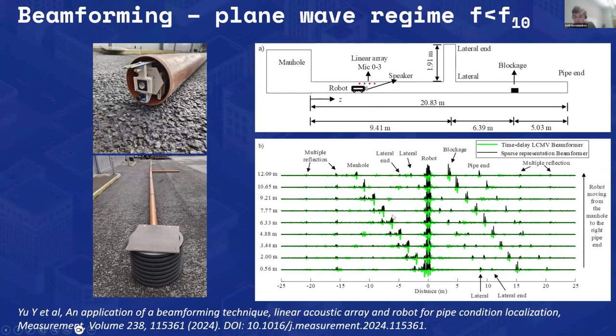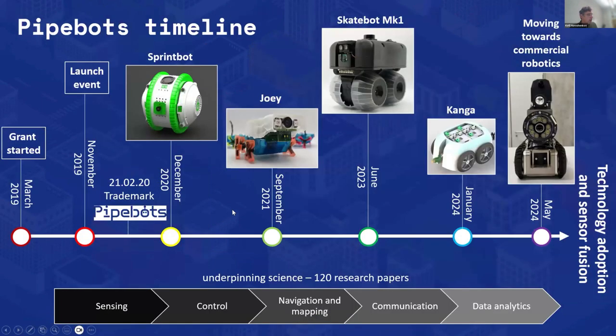With this arrangement, we can also do exactly what I showed on previous slides. We can do mobile compensation, and we can also do the separation of the reflections coming from the front of the robot from the reflections coming from the back of the robot. That has now been implemented on the Minicam robot, which we are building in collaboration with Northumbrian Water and Minicam.